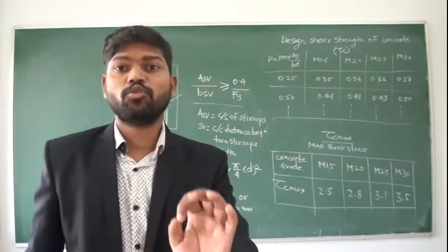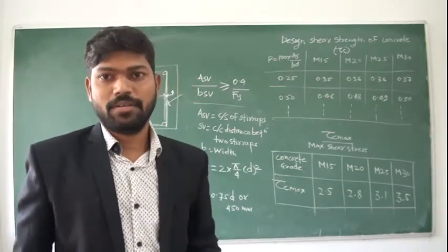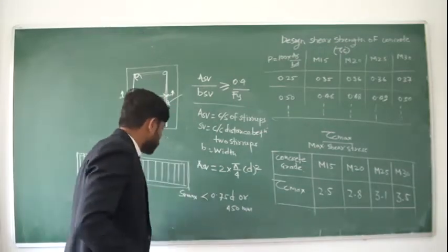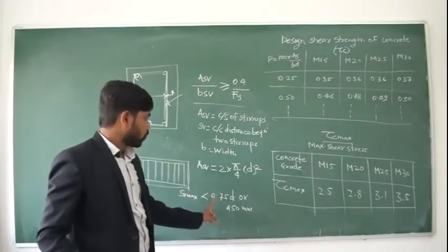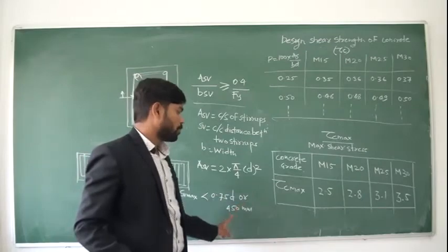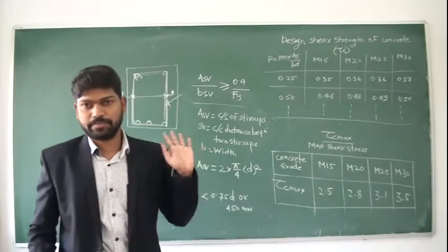Okay, that you have to provide to your site engineer. So that spacing should not exceed this 0.75 d or 450 mm in any case.